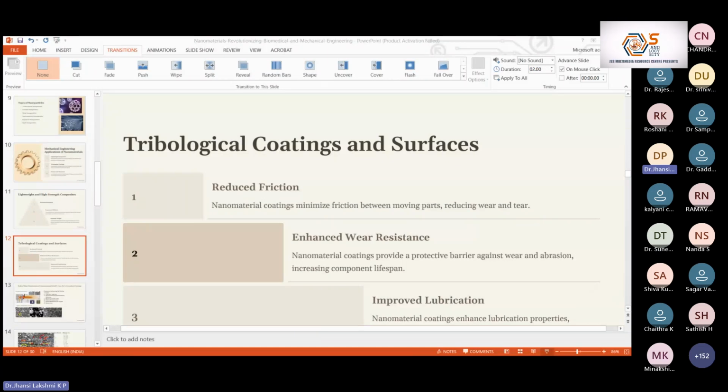If we use that pollutant, the cenosphere and fly ash are already widely used in civil engineering applications to prepare roads also. In some places they have even laid roads using this fly ash. In coatings also, the cenosphere is used in little proportions. They comprise mainly oxides of silicon, aluminium, and mullite. They have excellent thermal conductivity and a low coefficient of thermal expansion. Because of these properties, it makes a promising material for a coating.